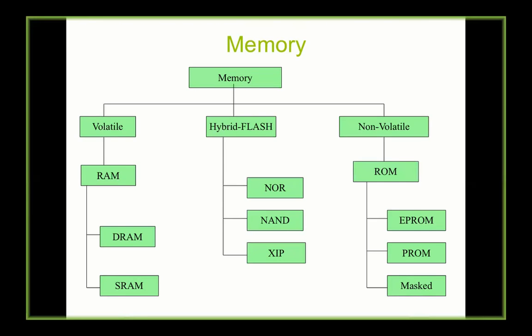So let me tell you, refreshment requires waiting, and the cycles of waiting can be achieved by having a delay generator attached to it. Hence you explicitly require one dedicated timer which will do this job, and that's the answer. It means a DRAM must be connected not to a memory controller, as somebody said. No. It will be connected to a clock, an extra timer, via which you will refresh it, right?